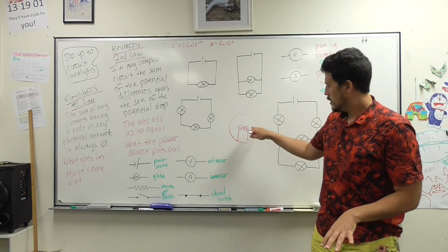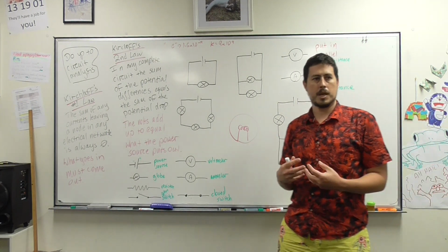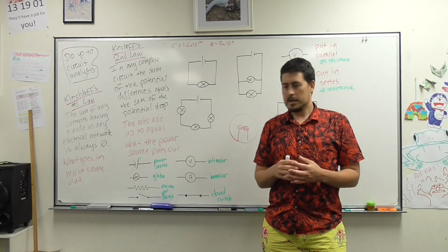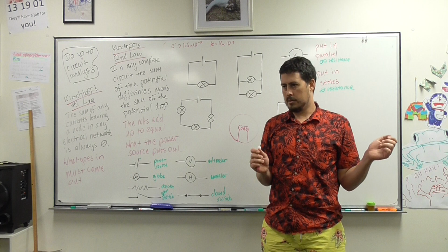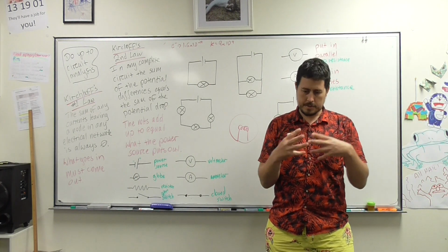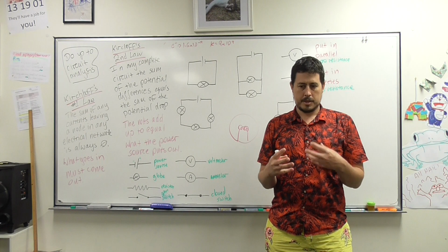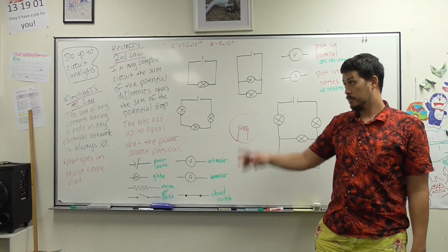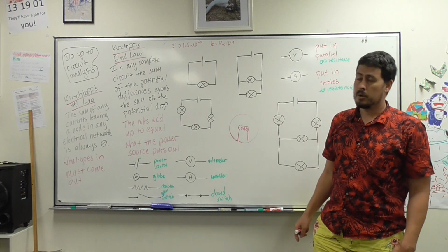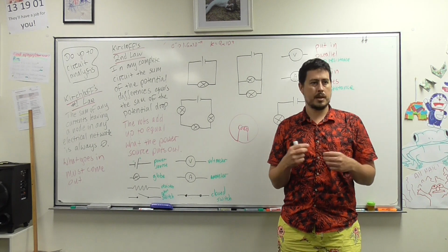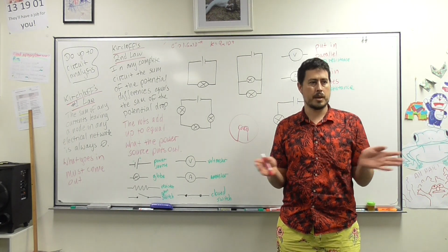Tungsten's a very hardy metal because when you're heating it up a lot, it is quite degrading at the microscopic level, and eventually that globe will break, either through too much power, or it's burnt, or it's given off so much light that it's had enough. They fill the globe with an inert gas like argon or neon so that you don't get oxygen oxidizing with the heat and the tungsten filament, causing it to break.